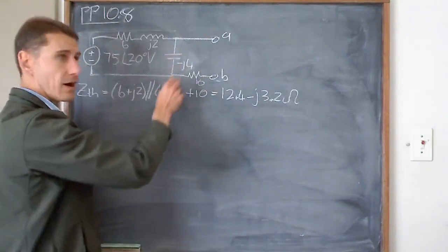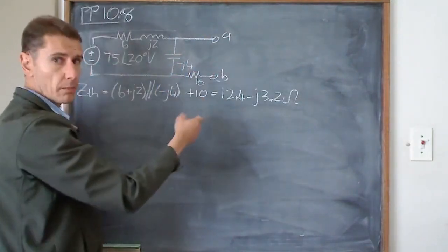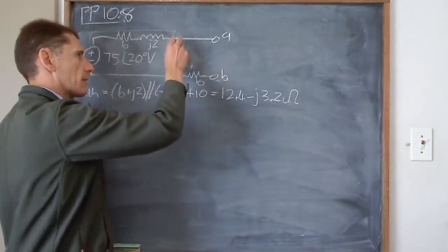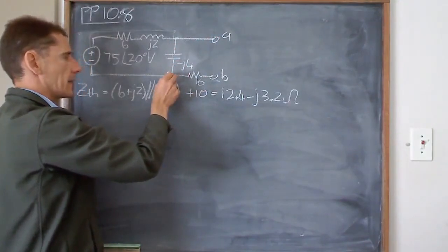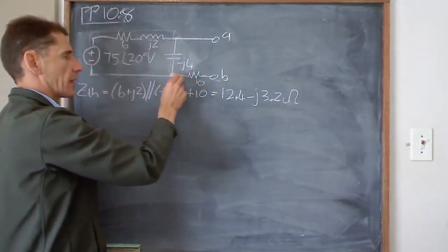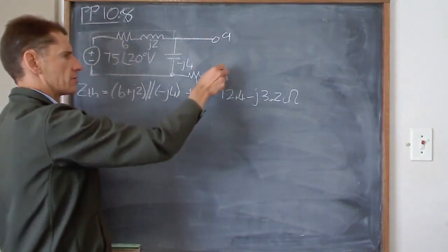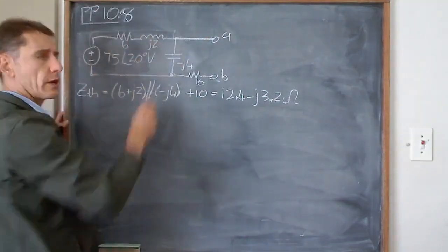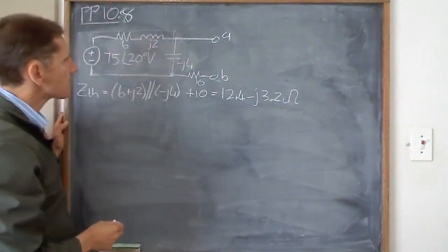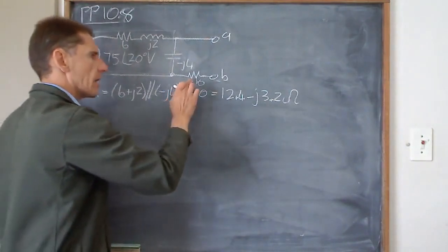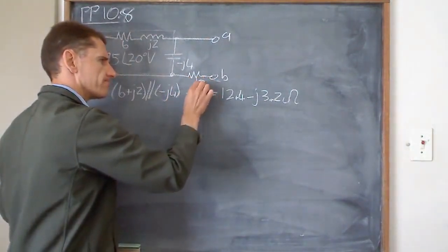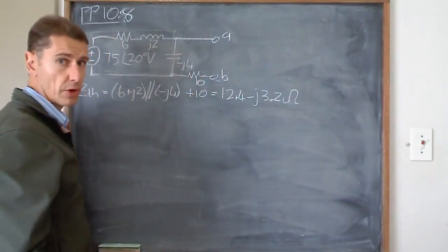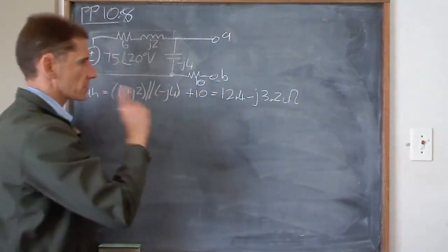Everything has to go down. Why? Big hole, big problem. You can't have any current flowing through that. So all of the current comes down through the cap and then gets to this point again. But wait a minute, there's no current flowing through the open circuit, so no current through the 10 ohms. So you actually just have this one loop where current is flowing. If there's no current flowing through this 10 ohms, what's the voltage drop across it? Nothing. No current, no voltage.